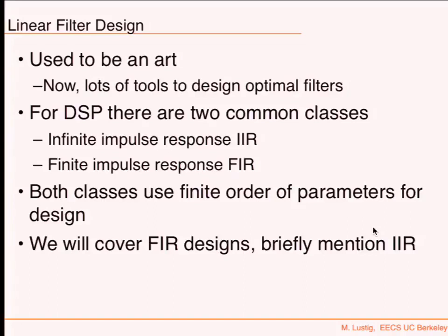So in a lot of cases right now, people are still going back and using FIR designs. The techniques used to design IIRs are mostly based on the continuous domain, which you translate into the discrete domain, whereas FIR designs are completely discrete, which I think is quite powerful in that sense.